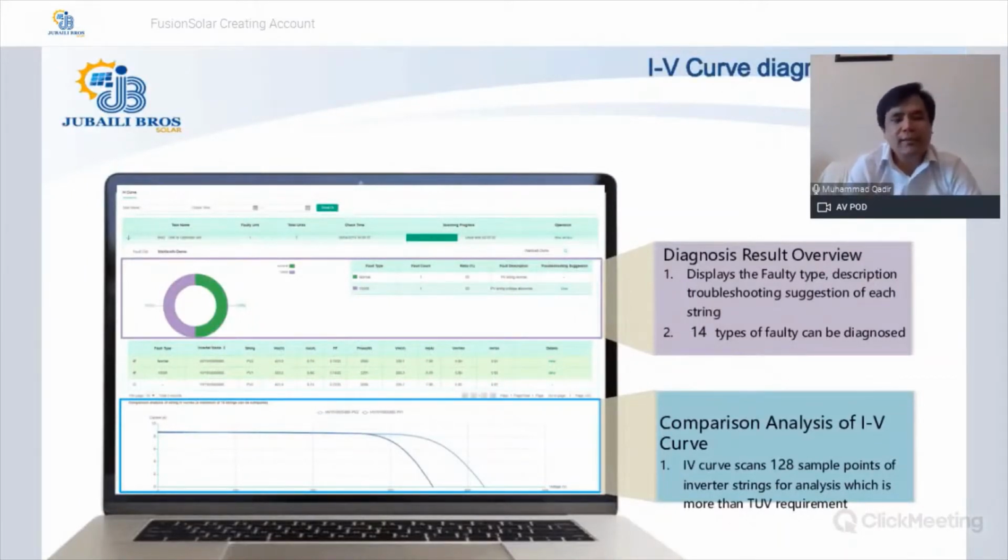So after the analysis, you will get the IV curve diagnosis report. This report will show you which strings are healthy and which strings are having faults. The faults could be of 14 different types which FusionSolar can detect. This window will display the faulty string. It will show you a quick description and also the troubleshooting procedure that you can follow in order to mitigate the issue.